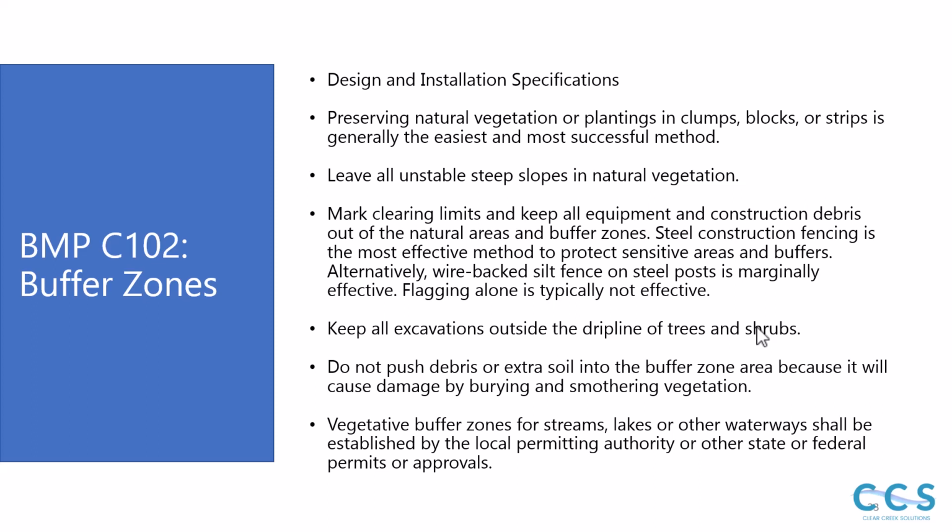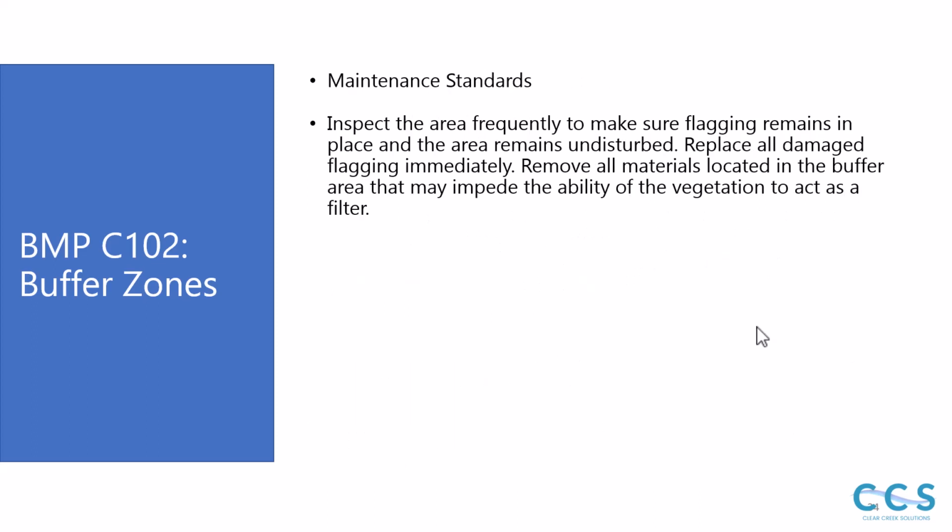Do not push debris or extra soil into the buffer zone area because it will cause damage by burying and smothering. And vegetative buffer zones for streams, lakes, or other waterways shall be established by the local permitting authority or other state or federal permits or approvals.